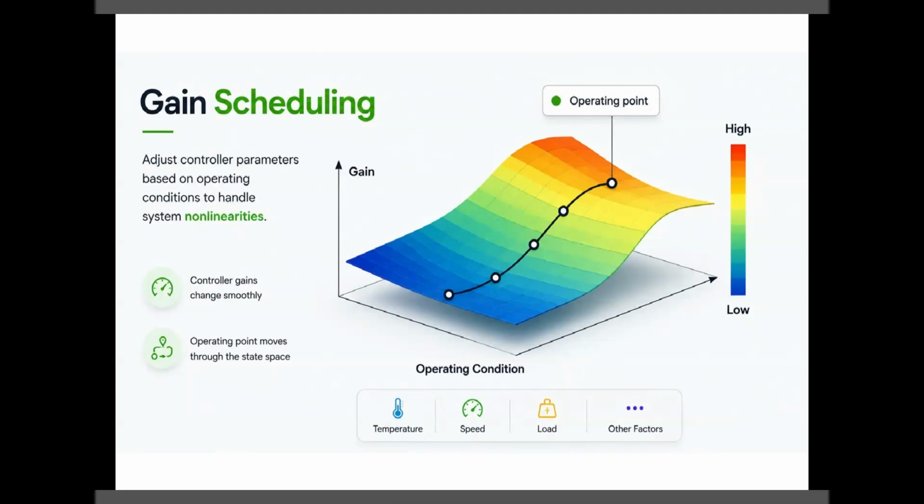In early implementations, this was done by switching between predefined sets of controller gains. Modern implementations go one step further. Rather than switching abruptly, they smoothly interpolate between neighboring controllers, allowing the gains to change continuously as the system evolves.